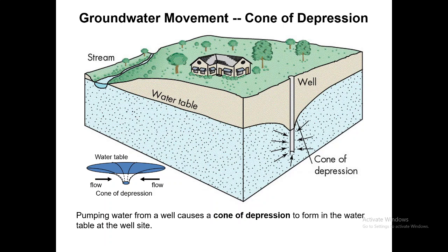And one more thing is that we are going to obtain it in the form of contours. This is only one direction, two directions in which we are watching it, and if we are observing it from the top, we will be observing it in the form of circles, and those circles will be actually the contours of water table elevation, water table head.